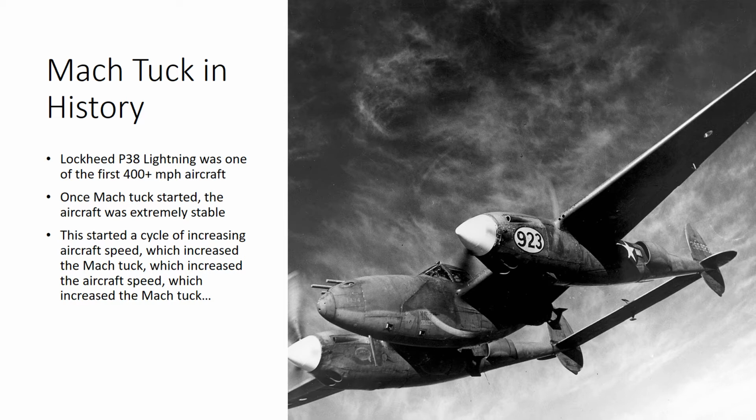Once Mach tuck started, the aircraft became extremely stable in this configuration, and it was difficult to have enough control authority to leave this cycle of increasing airspeed, which increases Mach tuck, which increases the airspeed more, which increases the effect of Mach tuck more, and so on. And so we knew that we needed to find some way to mitigate the effects of Mach tuck.